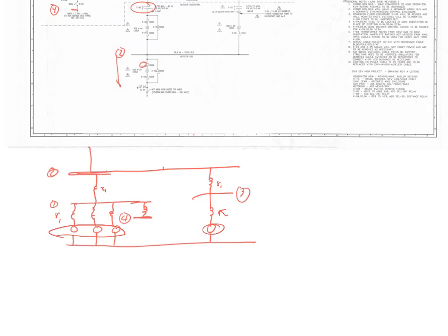That's because all these inductors in here store energy, and they can dump energy out to increase the fault currents. So when you're looking at fault currents at a very short time frame, like half a cycle after the fault has occurred, you're looking at peak currents. That's what the system has to withstand. That's called the withstand rating. But then maybe 2 or 3 cycles later, you actually have what's called an interrupt rating. What the breaker has to withstand is different than what it interrupts, because of that DC decay, that exponential decay.